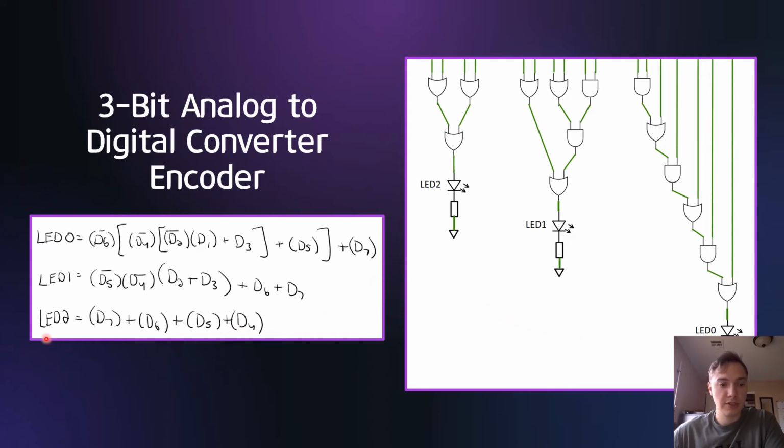So the expression for LED2 would be this, and that's just 3 OR gates put together, connected to these comparators. So I did that for all 3. Like the second one has 3 OR gates and 2 AND gates. I connected them as well. So I know I could have simplified these further, I think a little bit, but I was fine with the AND and OR gates only.